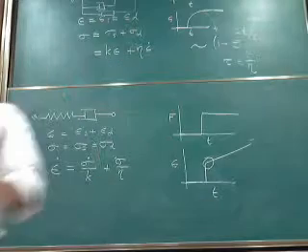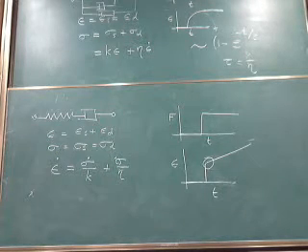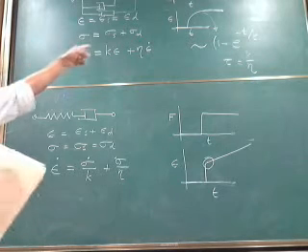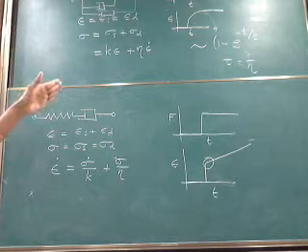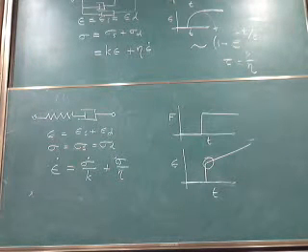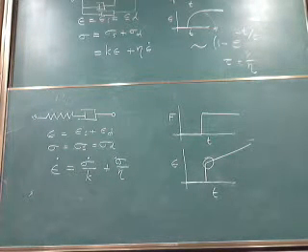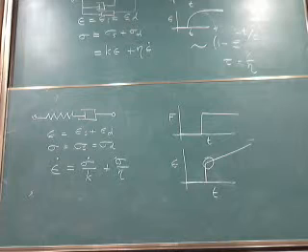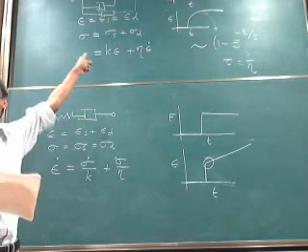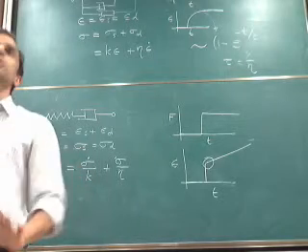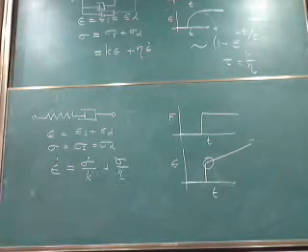If I take t equals 0 and ask what is the extension, that gives me the spring constant. And in the other case, I go to t much larger than the relaxation time, and then I ask what is the extension. Even if you are in a viscoelastic medium, you can very precisely measure the elastic component without interference from the viscous component, if your system can be modeled in this way or that way. Most real materials are more complicated than that.